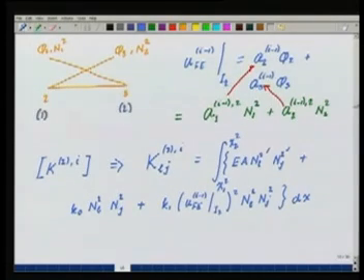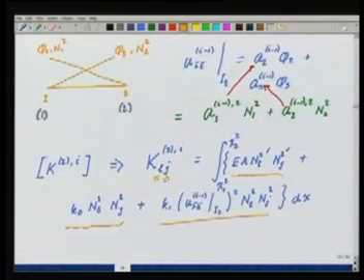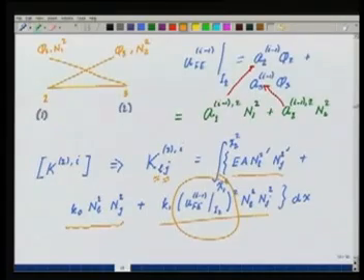Okay. So here this is a crucial difference from what we had done till now. This part we had already handled. And if I can do this, now how will I do the assembly? Again I will go to what this l corresponds to globally, what this j corresponds to globally, and that row and that column I am going to assemble it in. So for example, l equal to 1 will correspond to global 2, and j equal to 2 will correspond to global 3. So everything remains the same. The only thing is that I have to carry this information from the previous step and use it here.